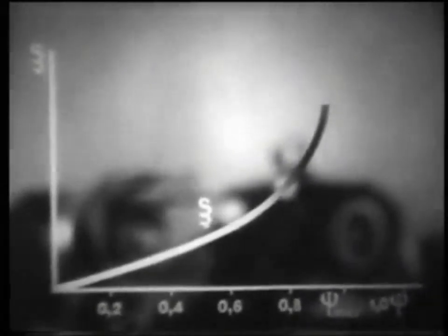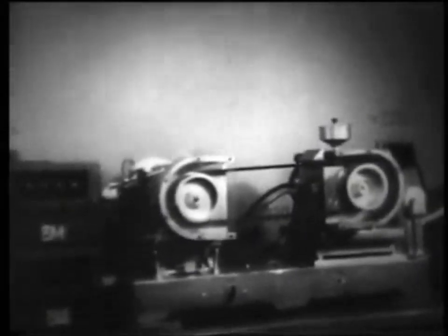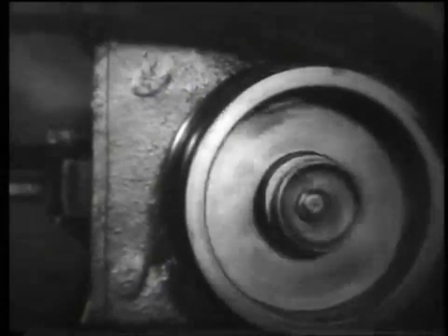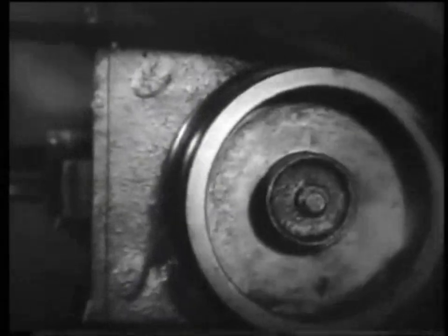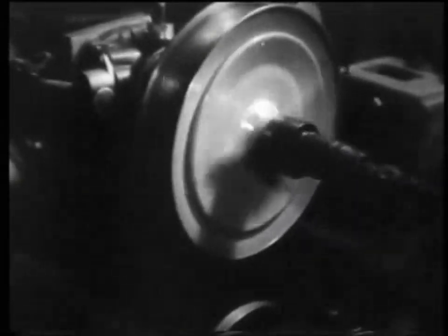With an increase in the load, the speed loss increases sharply, and at maximum load, the belt slips. In V-belt gears, especially in variators, additional speed losses occur due to transverse compression and radial movement of the belt.